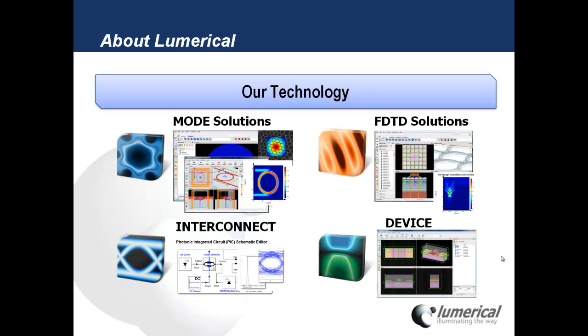And then Device, also added in 2012, about 5 months ago, is an electrical solver which allows us to solve for the electrical properties of devices. And so it's often used in conjunction with FDTD Solutions or Mode Solutions in order to solve for devices like CMOS image sensors, solar cells, high-speed photo detectors for silicon photonics applications, and also Mach-Zehnder modulators.